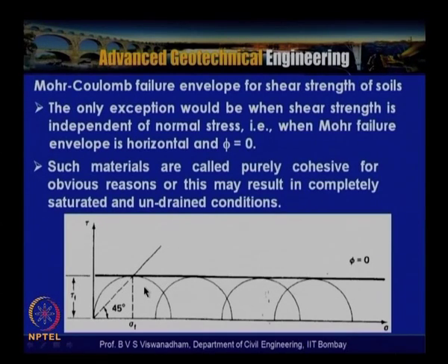Such materials are called purely cohesive, or this may result in completely saturated or undrained conditions. These materials are called purely cohesive soils or pure clay soils. When they exhibit this type of behavior, the failure plane occurs along the plane of maximum shear stress.